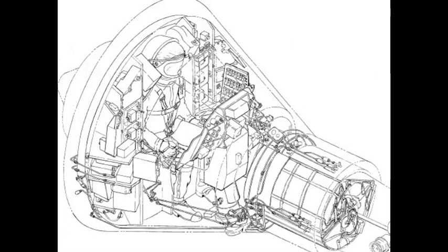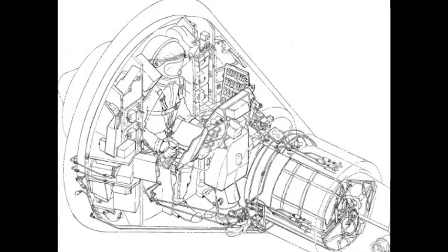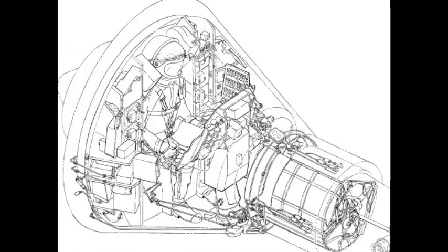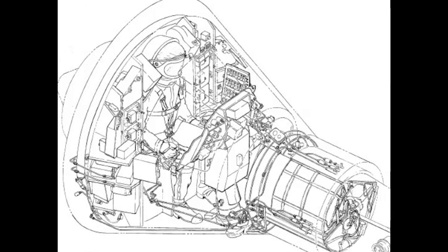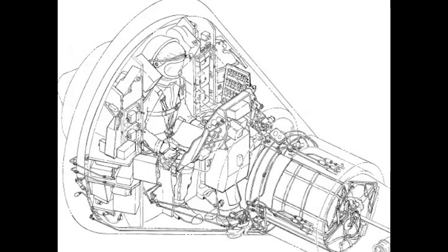A blanket of thermoflex insulation is bonded in between the hat stringers to the outer, beaded, conical skin. Thermoflex insulation is also installed over the hat sections and covered with a shingle arrangement. The shingle arrangement is similar to the shingle installation used on the recovery system compartment.